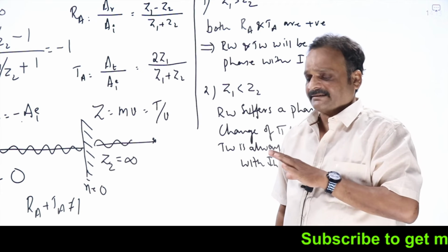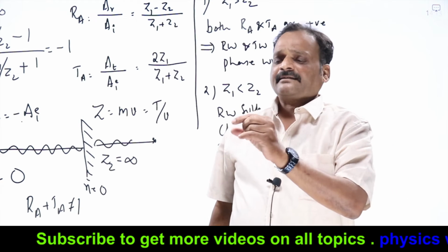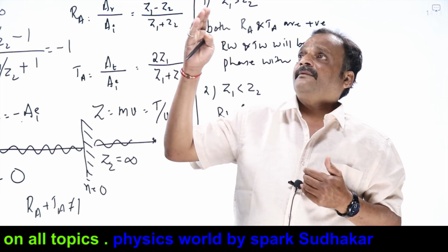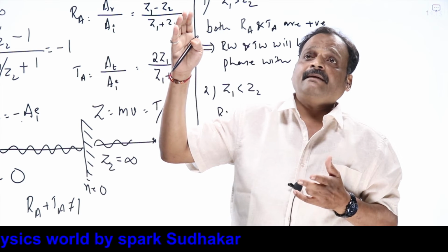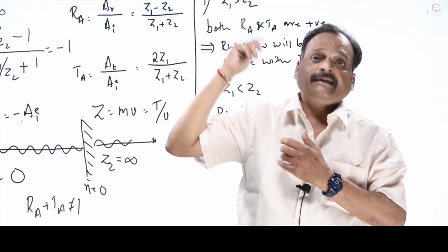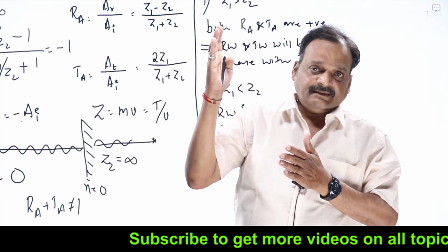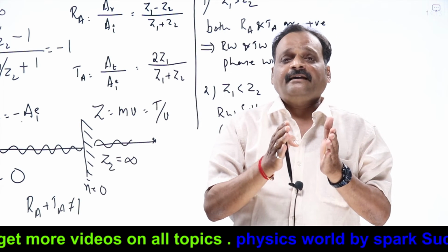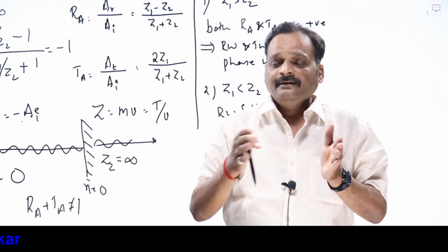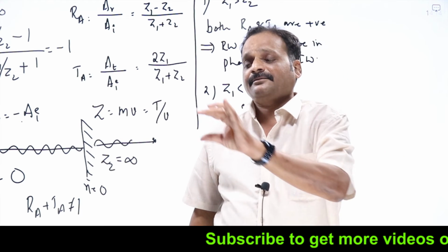Now, in some electronic circuits, I want to send a signal from one stage amplifier to another stage, in cascaded stage amplifiers. From the first stage, I want 10,000 or 1 million times amplification. 0.1 microvolt should be amplified to 100 volts, which means 10 to the power 7 or 10 to the power 8 times amplification is required. In one stage, that much amplification factor is not possible. So people amplify it 100 times, then 100 to 10,000, then 10,000 to 10 lakhs, in 3-4 different stages. The signal has to be sent from one stage to another, like that.